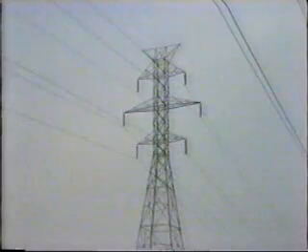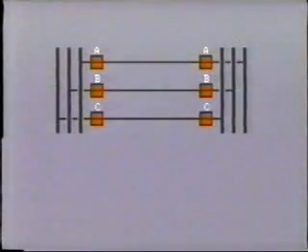Experience shows us that most temporary faults occur on one conductor only, giving us a single phase-to-ground fault. For this reason, many installations choose to trip the faulted phase only. The pilot protection is set up to trip both ends of the line, but on the faulty phase only.